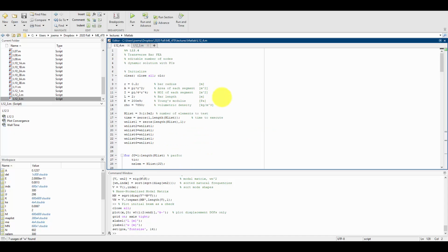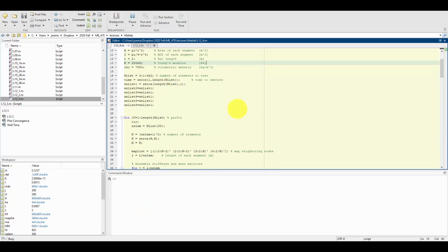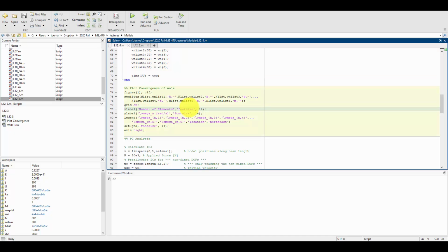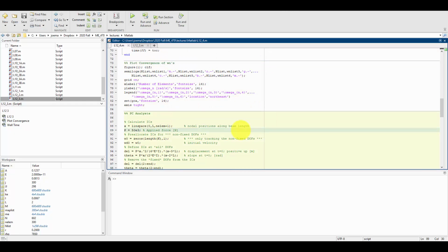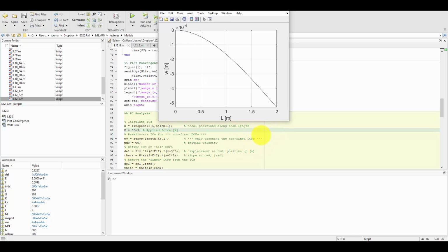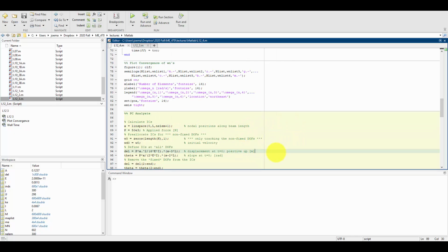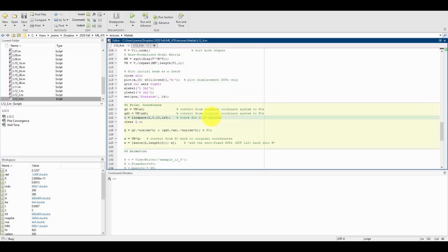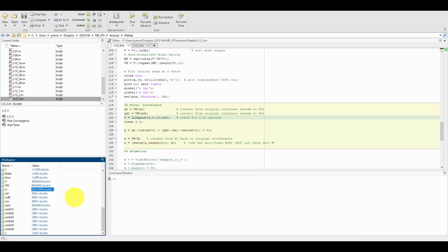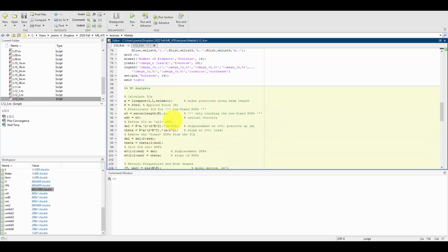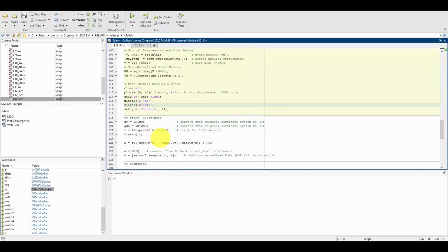So I'm going to go through and run all of these steps to see all the sizes that we come up with. So again, going back through, we have convergence, now doing that principal coordinate analysis step, making sure that our initial conditions looked correct, and they did. Solving for our principal coordinates, and now that step is done, and we can look at W. W now is 602 because that's the number of degrees of freedom I have when I had 300 elements by 1,000, and that 1,000 is coming from here. I was doing this for 1,000 time steps between 0 and 0.1 seconds.